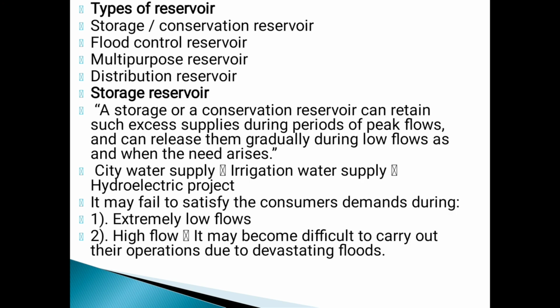Next, what are the types of reservoirs? They are storage and conservation reservoir, flood control reservoir, multi-purpose reservoir, and distribution reservoir. At first, in a storage reservoir, a storage or conservation reservoir can retain such excess supplies during periods of peak flow and can release them gradually during low flows as when the need arises. City water supply, irrigation water supply, hydroelectric projects. Without it, supply may fail to satisfy the consumer demands during extremely low flows, and during high flows it may become difficult to carry out operation due to devastating flood.